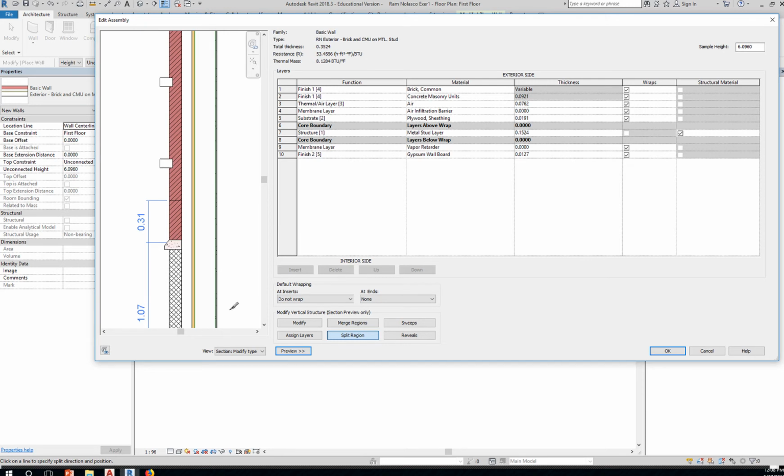So split and place this, or hover. Now, when you do that, you can modify the height, since normally you won't be at the exact height. You can click on Modify and then click on that line segment that you have created. That's the split line. Once you have done that, you can then click on the value and put an exact value.